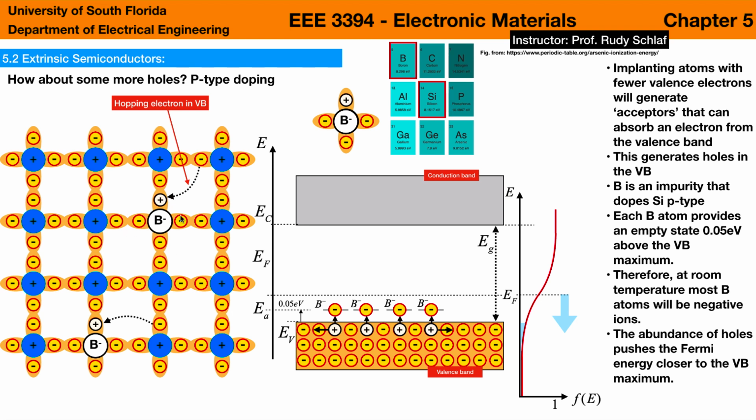So when we integrate boron into the silicon matrix, the boron can make 3 successful bonds with the surrounding silicon atoms, while it draws a blank with the 4th one because it doesn't have an electron. So putting a boron into the silicon matrix introduces a hole.